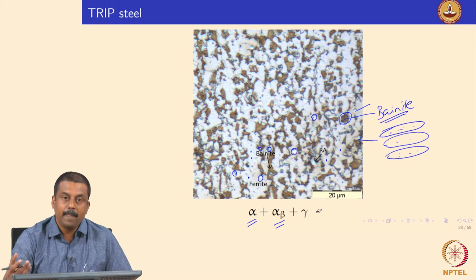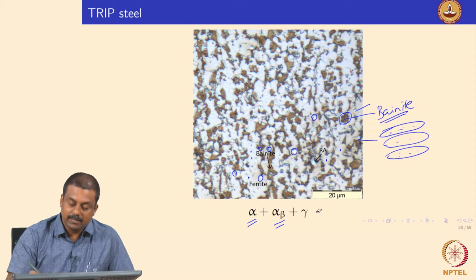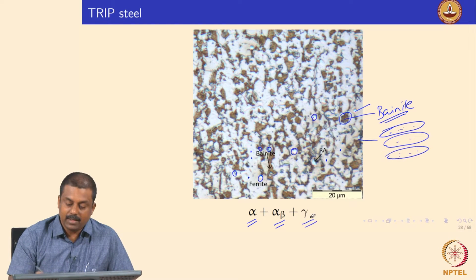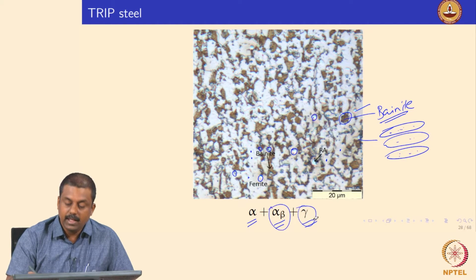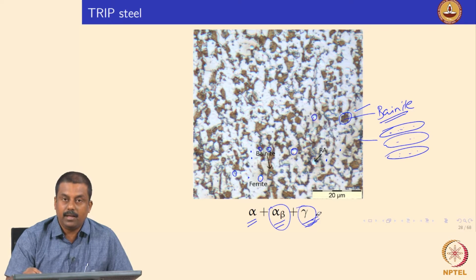during applications. So this microstructure of ferrite and bainite without cementite and the retained austenite is very attractive for automotive applications because of the strength which is achieved from the alloying elements as well as the presence of bainite and the supersaturated bainite, and the superior elongation given by the stress induced transformation of austenite to martensite. Okay.